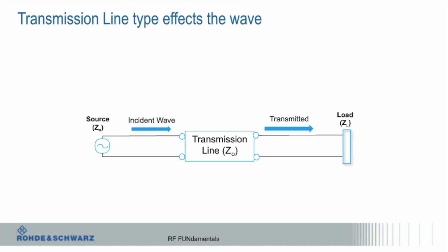Okay, so let's see. Transmission line, waveguide. So these are some of the waveguide bands, and I would find it unlikely most people here would ever deal with these. But these are some of the different types of waveguides. This is the bandwidth. Waveguides act like a bandpass filter. So when you get outside the bandwidth of that waveguide, it pretty much doesn't pass anything. And there's the band names. Again, more often than not, these are used by satellite people. They like those band nomenclatures, and they do high power too.